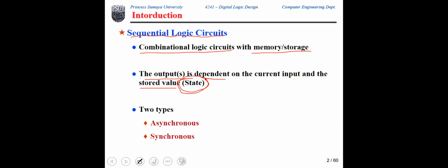And whenever you get confused, always remember our previous example, the counter. What do you need to implement such a circuit? You need to know if the input is 1, and you need to know what is the current count value, which we call the current state or the present state. الحالة الحالية. What is the circuit remembering now? So this is called the state, or technically the present state. So this is the difference between sequential logic and combinational logic. Sequential logic is technically combinational logic plus memory.